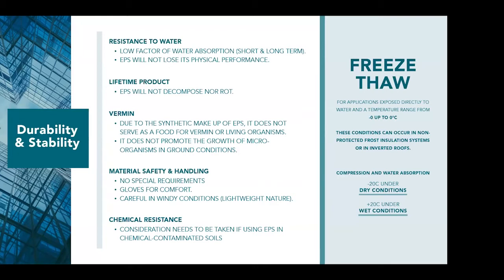If we look at freeze thaw in masonry, obviously we all know about that at the moment. There's a lot of talk in the industry. It's not so good. So EPS performs very, very well there. A regular question we get is about vermin. If you're burying an EPS in the ground, is this an issue? Because EPS is a synthetic type of build-up, it doesn't have an attraction to any vermin, and it also doesn't promote the growth of microorganisms.